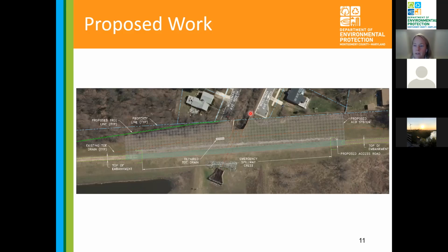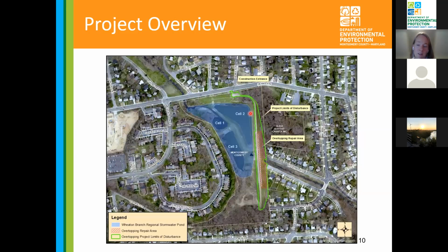And you'll see those around a lot of our storm drain outfalls. Anywhere there's a pipe that outflows into a stream, you'll see kind of concrete wings that come out the side of the pipe outfall area. If you take a look at some you may be passing by one day along the street. Yeah, they can be very, very large or very, very small. And this is kind of a weird geometry. Usually they're just a flat or like a winged section.